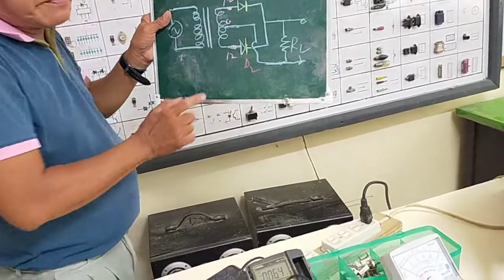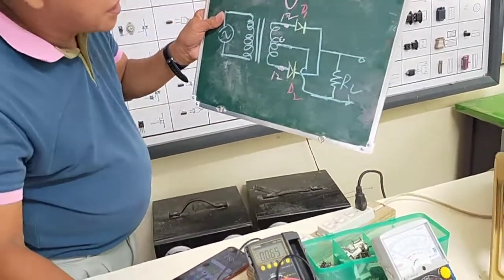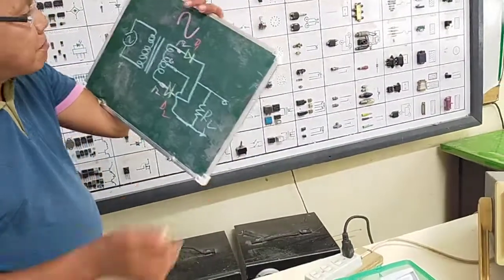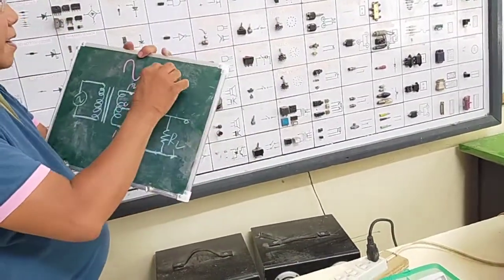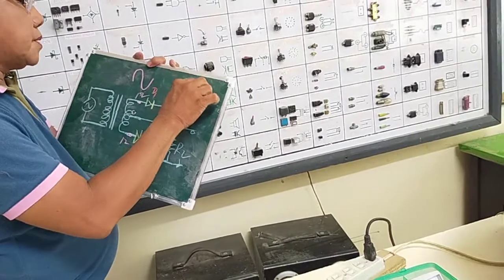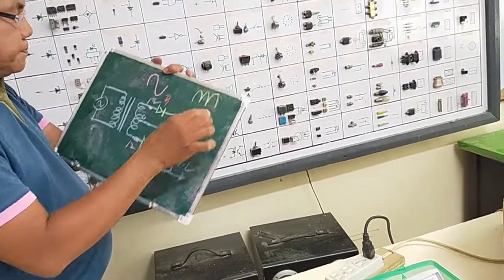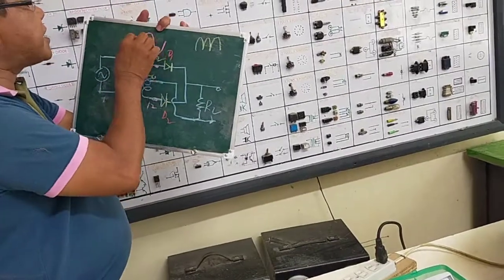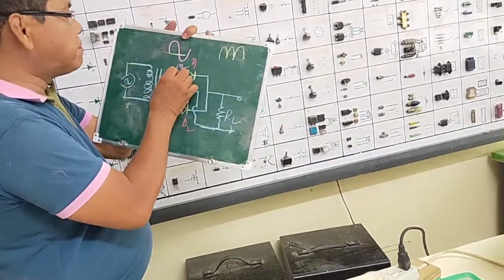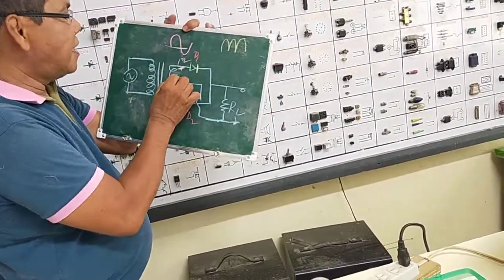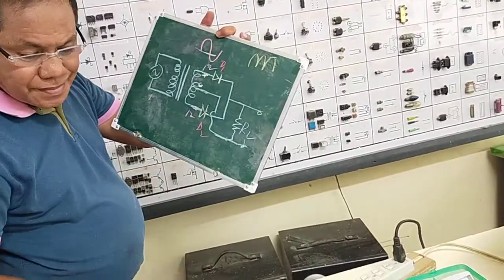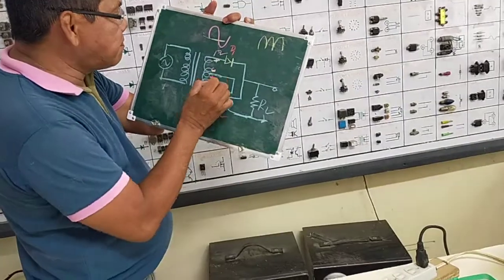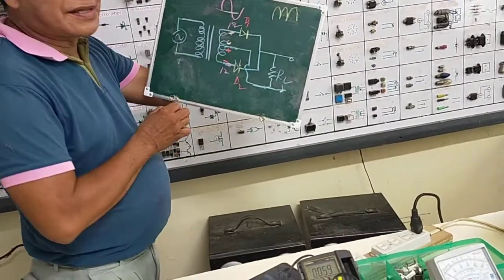It is a center tap type in the sense that there are three terminals at the secondary winding. Okay, it goes like this. Why it becomes full wave at the output, and it is 120 hertz. So, in the first half cycle, this must be positive here, and this center tap is negative. Then, the center tap is positive, and this should be negative.